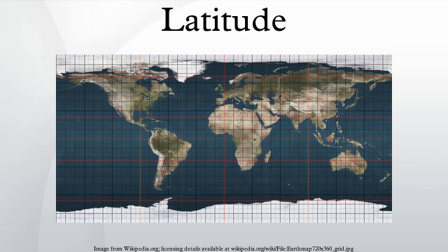The difference of the major and minor semi-axes is about 21 km, and as a fraction of the semi-major axis it equals the flattening. On a computer the ellipsoid could be sized as 300 px by 299 px. This would be indistinguishable from a sphere shown as 300 px by 300 px, so illustrations always exaggerate the flattening.